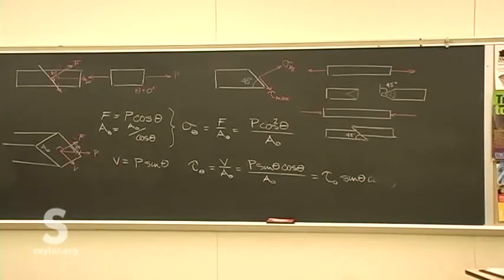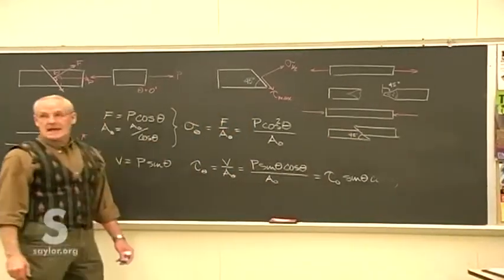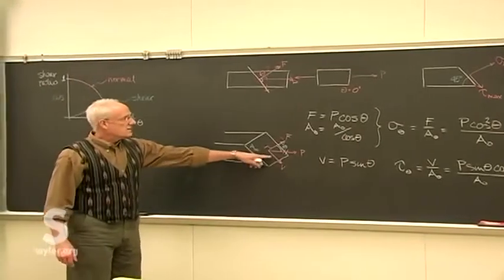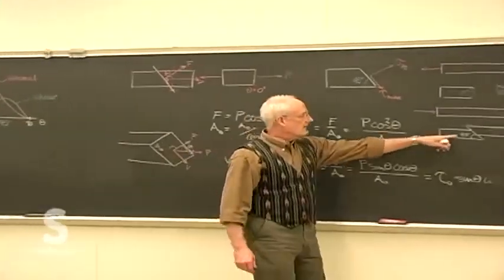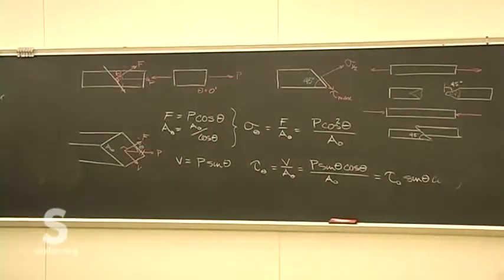Especially with wood, there's differences in the material throughout. It's not perfectly homogeneous, which is why it's not exactly 45 degrees. But that is where we predicted the maximum shear failure, and that's just what's seen when the piece does go to failure. So on Angel, go check out those 2 videos.